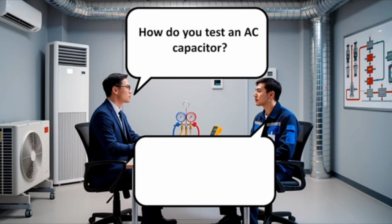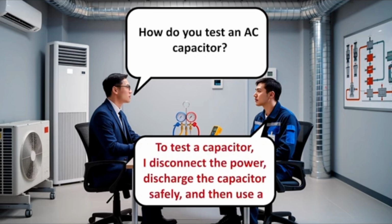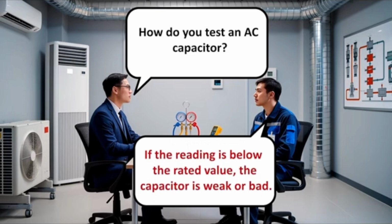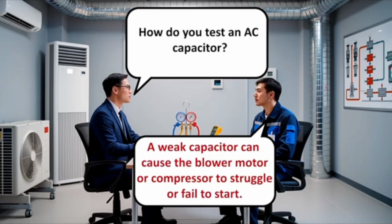How do you test an AC capacitor? To test a capacitor, I disconnect the power, discharge the capacitor safely, and then use a multimeter in microfarad mode. If the reading is below the rated value, the capacitor is weak or bad. A weak capacitor can cause the blower motor or compressor to struggle or fail to start.